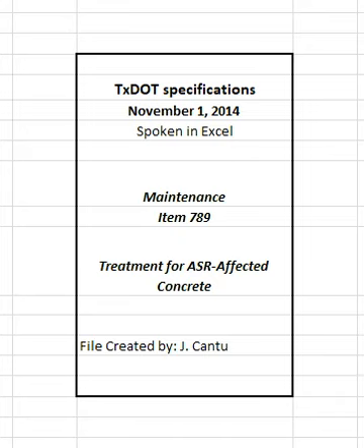4. Construction. Treat all areas as indicated on the plans or as directed. Apply the treatment in the following order if a carbon wrap is used as part of the ASR mitigation. Fill or inject the cracks with epoxy. Apply the wraps. Apply the primer.